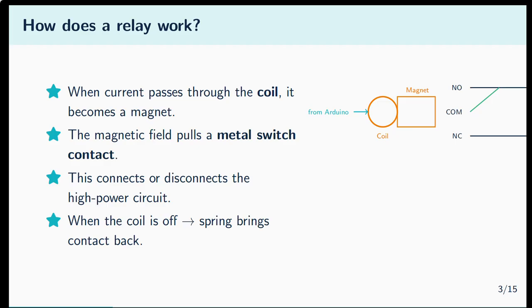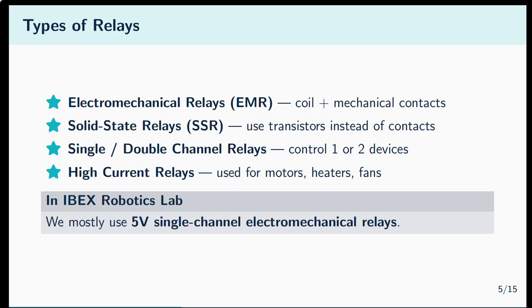Let's move towards the types of relay. Mainly relays are of two types, but you can also categorize them into four types. EMRs and SSRs. EMRs are basically the relays that we have just seen on Google. These relays are based on mechanical motion, right? I have explained to you that there are three pins. One is movable, that is the middle pin, and there are two pins on the left and right side of the movable pin. This whole concept is based on EMR technology, electromechanical relays.